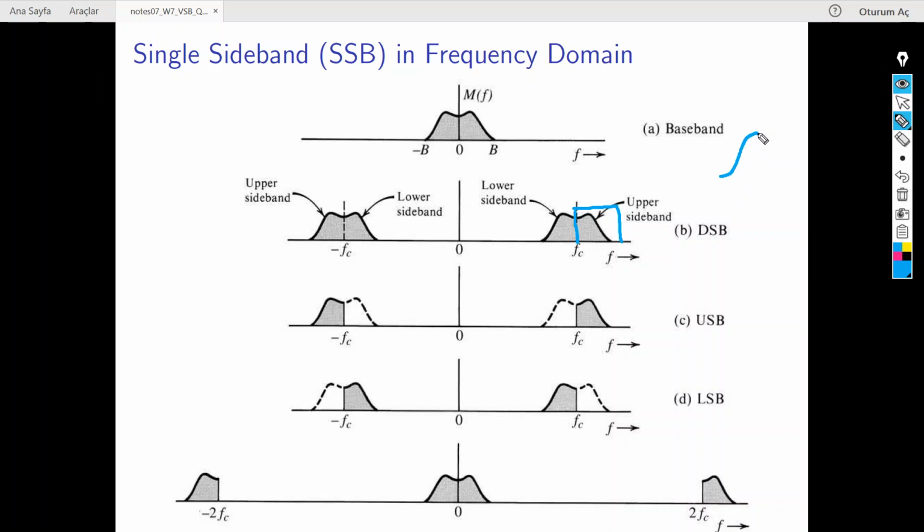You cannot make them exactly sharp like this, because to make them sharp like this, in the Fourier series analysis, you need to take components from minus infinity to infinity, and this is impossible. So what you do is just take the most important components, and these should not be that many, in order to be able to deal with them, manipulate them, and represent them. Due to not taking all the components that represent the Fourier series of the rect signal, you just take a few of them, and you end up having a filter like this.